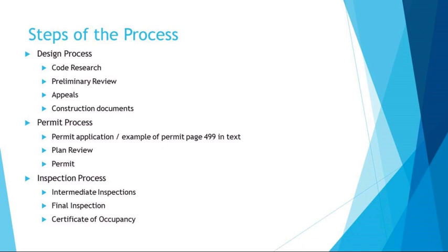A lot of times I go through, do preliminary drawings, then I review it with the code official. I take notes so that the necessary changes can be made to the design if they see something that jumps out at them. It's also important to prepare a summary of the meeting for the project records. After the meeting, send a copy of the summary to each attending code official and ask him or her either to sign off on the summary indicating acceptance or send written confirmation.